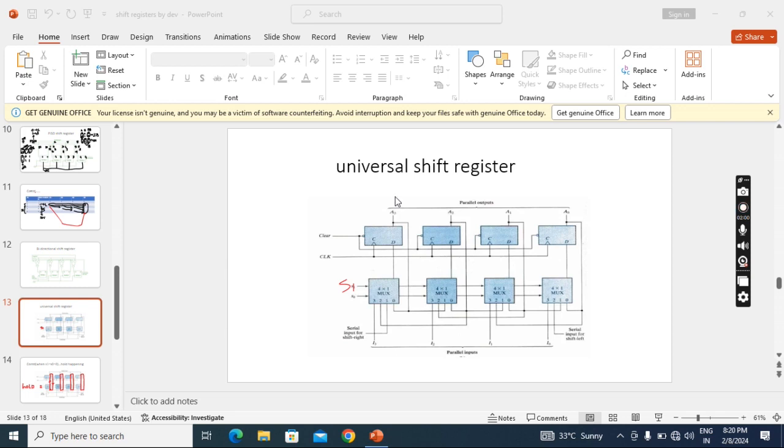At the output of all the flip-flops, we are taking the parallel output. And where are we giving the parallel input? At this place. We give the parallel input to the multiplexer, and take the parallel output from the D flip-flops. Because there are 4 data inputs to the multiplexer, we give it at this terminal, which is selected when both selects are 1 1. This is select 1 and this is select 0. These selects are connected commonly to all multiplexers.